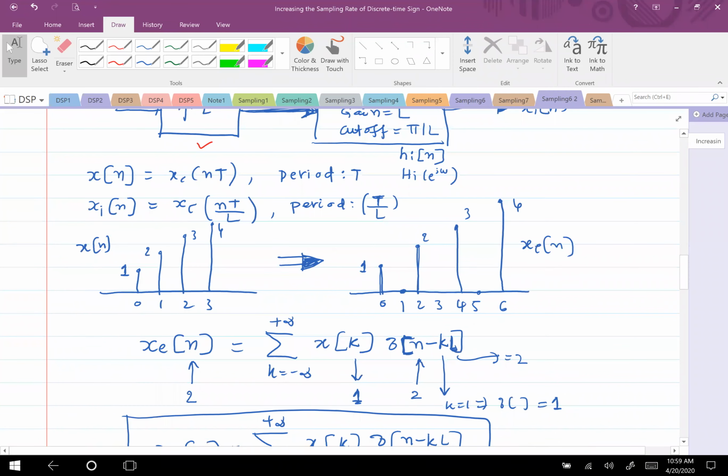All I wanted to emphasize here is the similarities between converting a continuous time signal into a discrete time signal and downsampling the signal. Similarly, given a discrete time signal, converting it to a continuous time signal has similarities with upsampling a discrete time signal. There are similarities as well as differences.